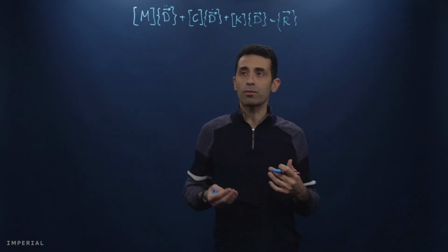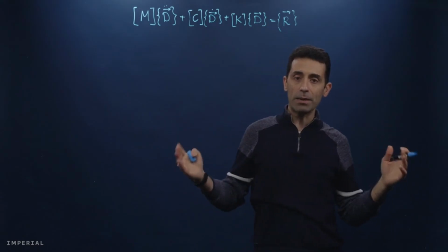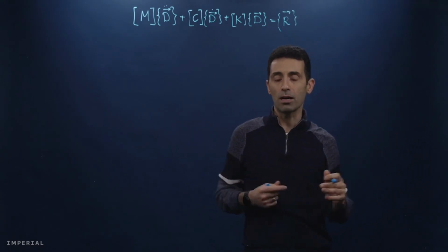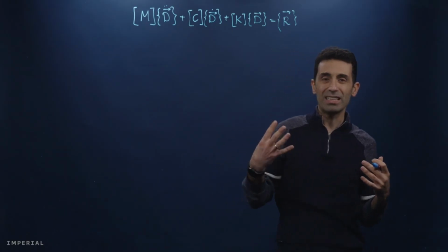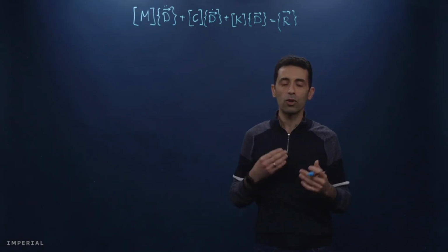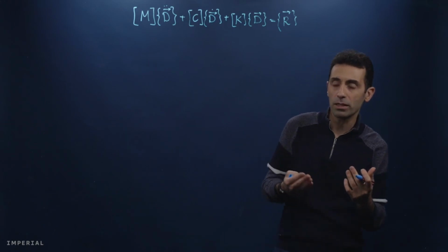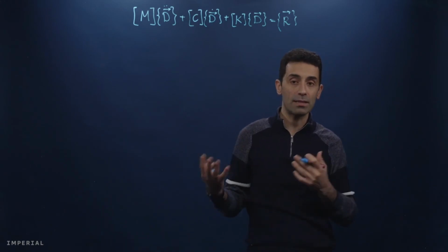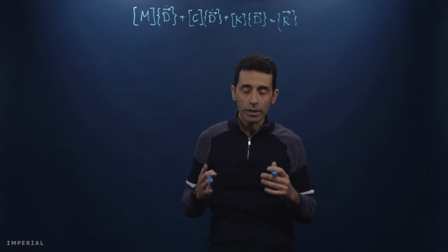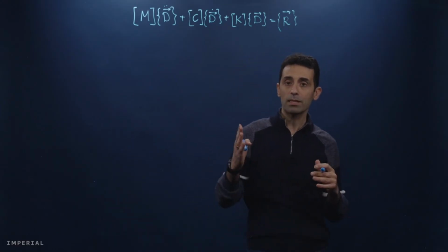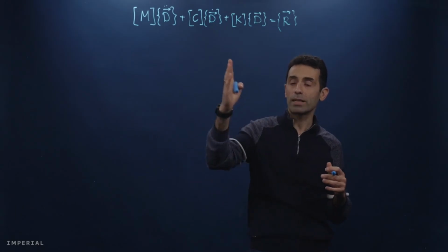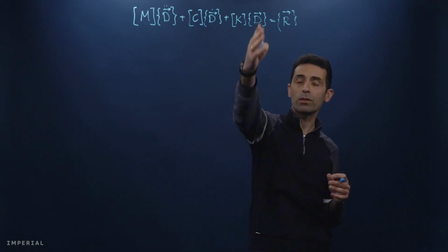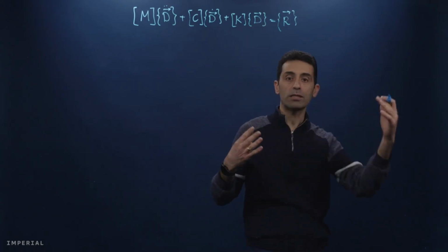When we want to solve this problem, you can imagine this is a dynamic problem. So loading is happening in a certain time. Imagine, like in impact analysis, we are often looking at something around 100 milliseconds or less. If it was blast, probably it was even less than a millisecond. So we are looking at different time scales, but what matters here is that the variables, like the field variable, which for us is the vector of nodal displacement, change with time.